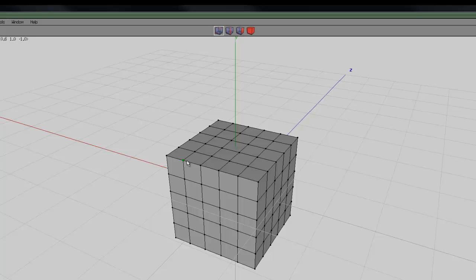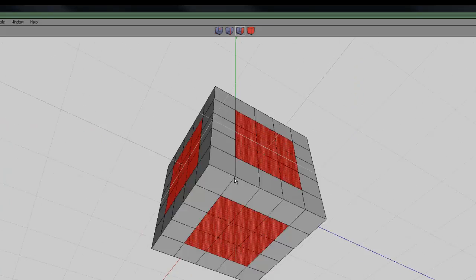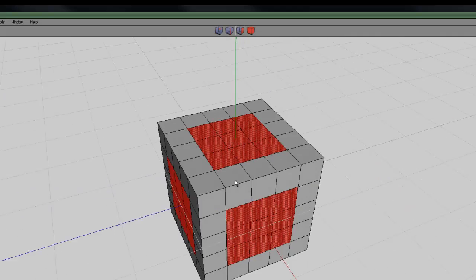what they call the vertex selection tool here, and select one of these vertexes and press I, and that will select all the identical ones, and you can see the corners have been excluded. Now if I use the minus key, it'll retreat the selection back until I've got only these 4 vertexes in the middle of each face, and then if I switch to face, that'll select all those faces. So that was just a way of selecting all the faces without having to select each face in turn, and then using the middle button you can go into rotate and select the other faces.